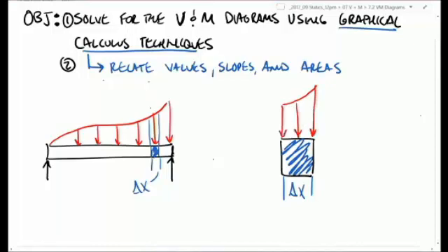So I could say that this is W as a function of x, the loading as a function of distance. And in all these problems, we're going to use an x-axis that just goes horizontal to the beam. I'll also say that for all shear moment diagrams, we'll be using horizontal beams, and that's it. Okay, just as we build this tool, we just focus on horizontal beams. And if I took two cuts, right, this is like one cut here and another cut there, I've exposed the forces that are inside that beam.